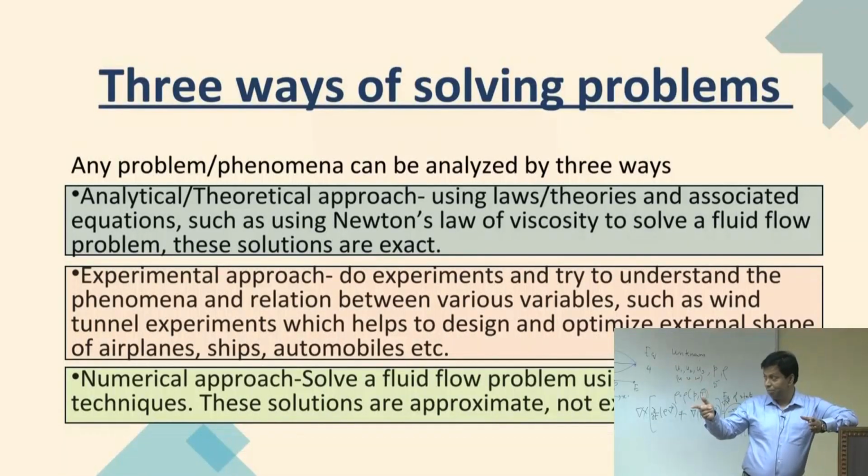For example, we mentioned that we have the unsteady term, the advection term, the pressure gradient term, and the viscous term. Okay. So during the unsteady flow development, in some stages some terms are important and some terms are not important. For example, very initially, when t is very small, the advection term is not important because the flow does not start. Mostly conduction is important. So at that time we can ignore the advection term, and then we can balance the unsteady term with the diffusion term.